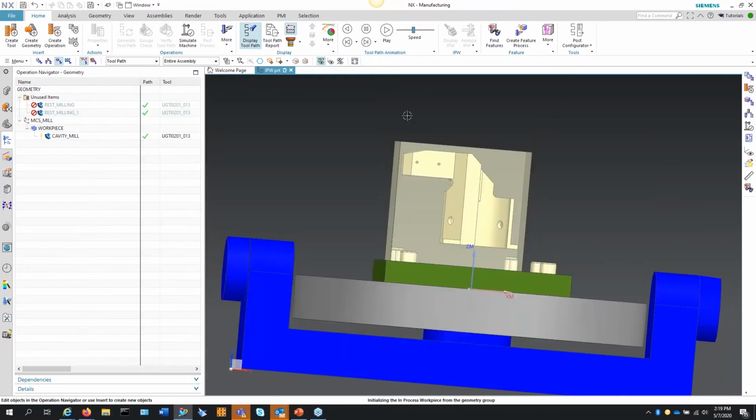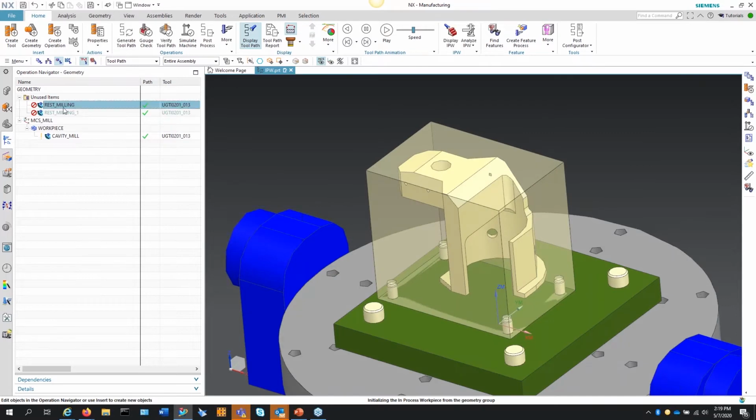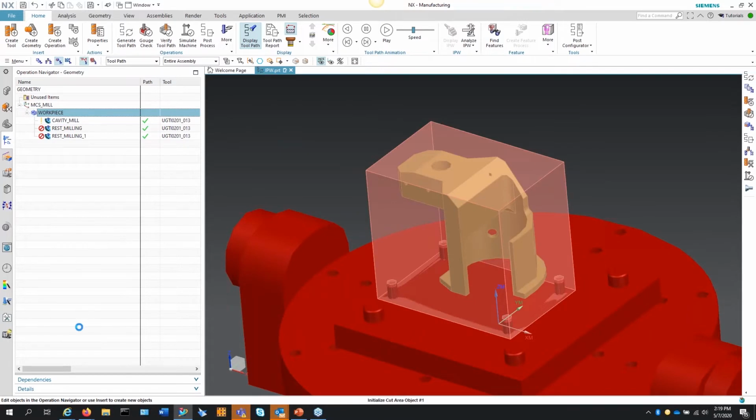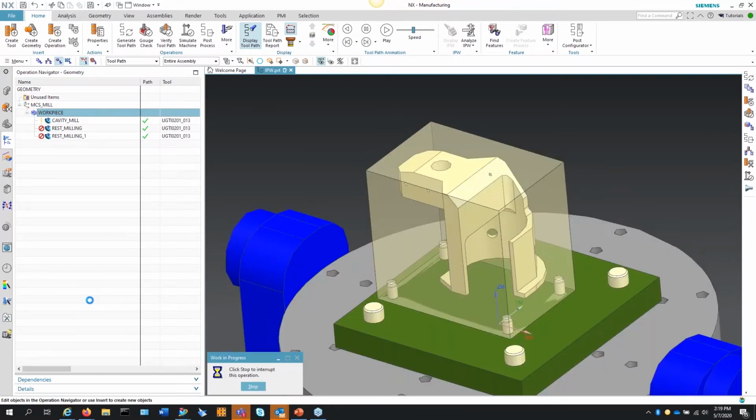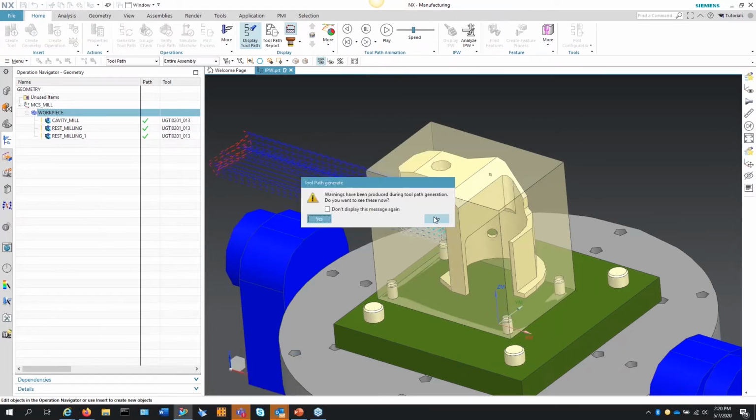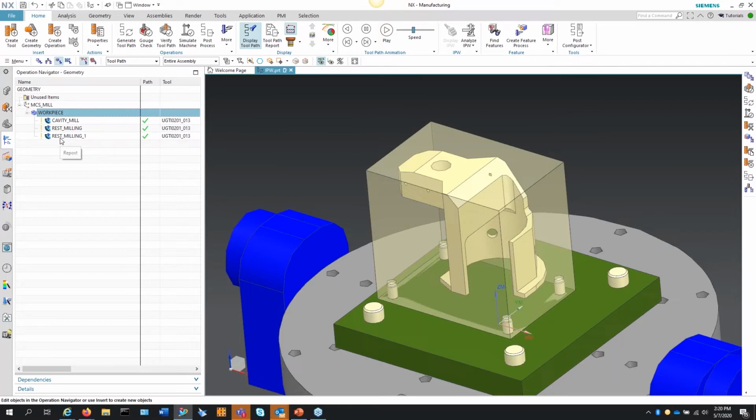So now I do not have a second operation. I'm going to put these back in place. Regenerate. I'll have my file called backup. And this is the best practice flow of how you should be creating manufacturing files within NX. So once this generates, you save it,